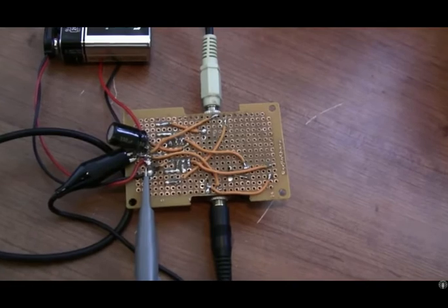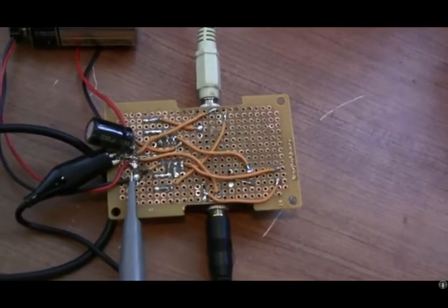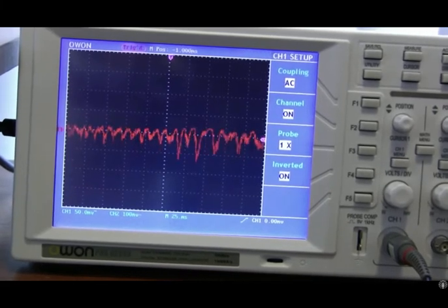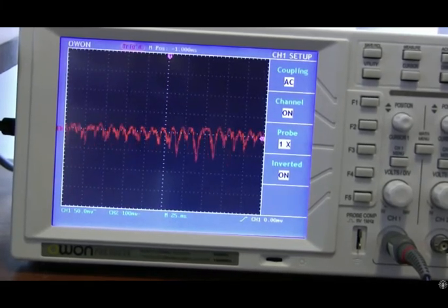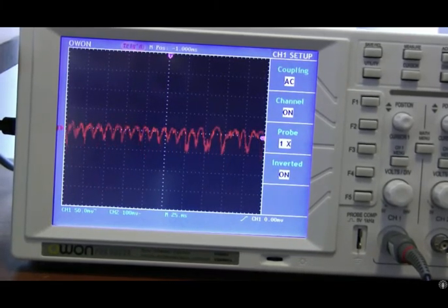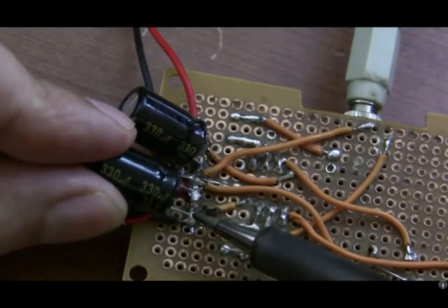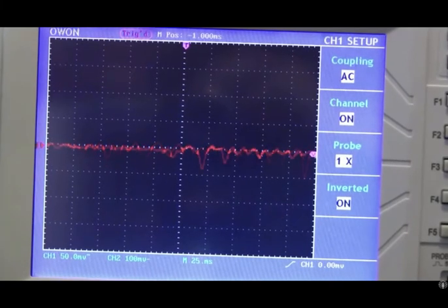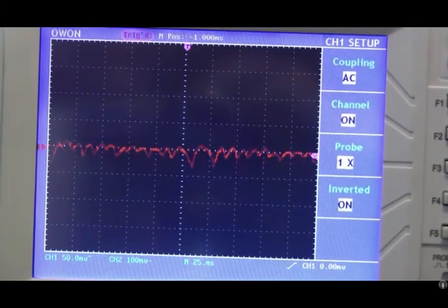Finally, I want to show you a real-world example on this headphone amplifier I built. You can see that when I crank up the volume, I'm getting massive fluctuations in the power supply voltages. So, what's the solution? I have to add some capacitors to smooth out that voltage. Now here's what it looks like after the capacitors are installed. Much better. And the sound will be better too.